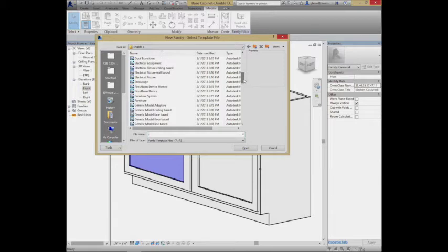There's this big issue of really what category things belong to. You figure out, oh, it's a piece of furniture, it's a piece of casework, it's a piece of whatever you want it to be. Okay, so we choose the overall category. A slight variation I want to let you know about is whether or not something is based or hosted on something or isn't. Let's look at the electrical fixtures. Maybe that'll be the easiest example.